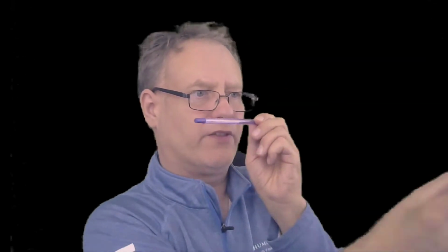There's a magnetic field that's here and here. That's either the north or the south, and this is the north or the south. Now we move this conductor up. Well, what happens is the EMF is actually pushing this way. And again, if we've got a closed loop, then there's current going that way too. Well, the whole concept of this going up and down all the time actually creates AC.